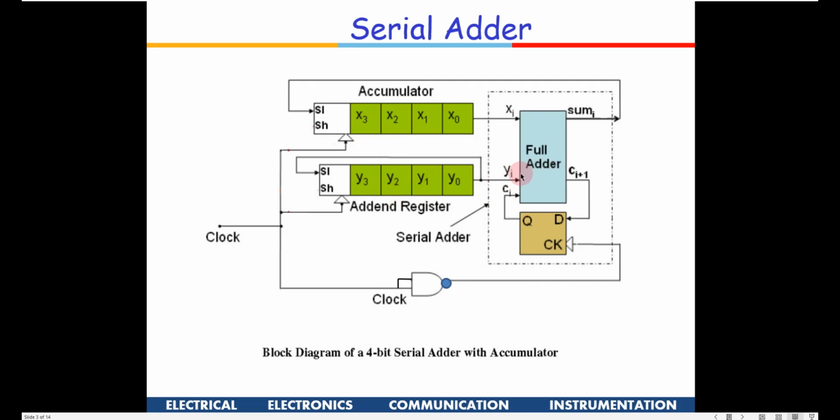So each time, the sum which is coming here is being pushed out here, right? So in 4 clock cycles, you will have the data pushed out here. And finally the carry will be available here. The sum will be available here, and the carry. So this is how an accumulator works: within the accumulator, the data will be from the sum. It will keep coming like this.